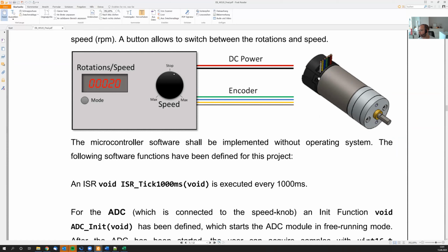You typically don't get 1 pulse per revolution, but typically 4, 32, or even way more. I once saw 1024 pulses per revolution. Crazy. But we need to do some math here to calculate that back to actual revolutions at the shaft of our motor.